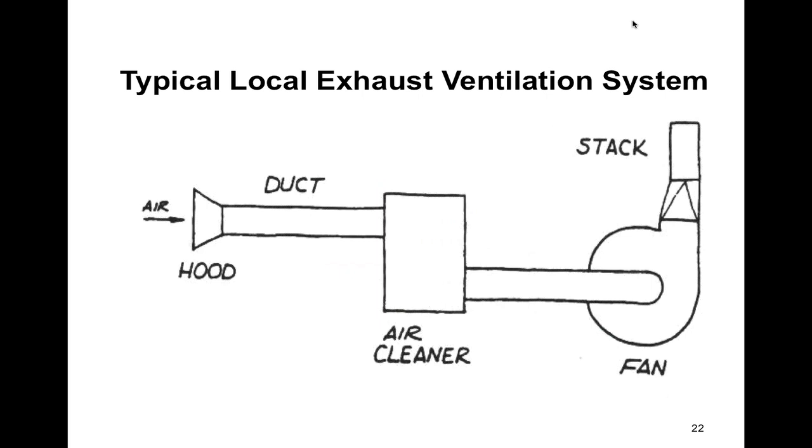So it's not always true, but generally true that you're working at a fixed location with a fixed hood. Local exhaust ventilation is usually provided when overexposure as a hazard may occur. In other words, in industry, if they don't need to spend the money, they're not going to spend the money. So usually you see a hood in a situation where there's a serious chance of exposure, right?